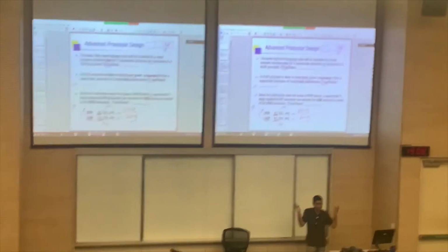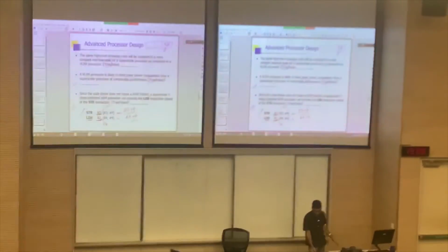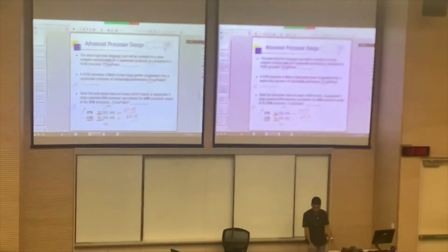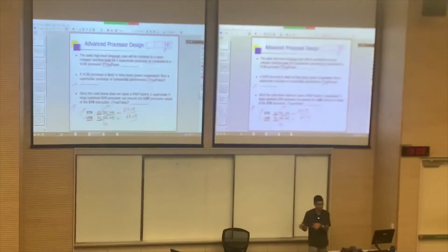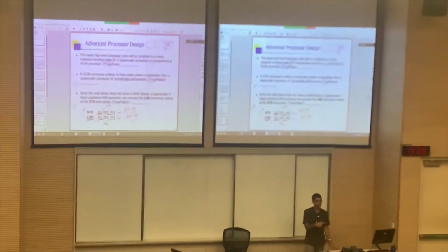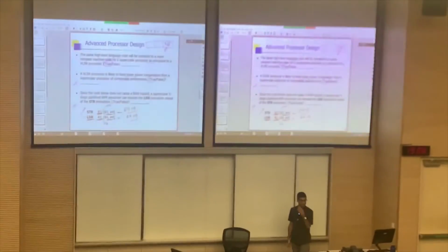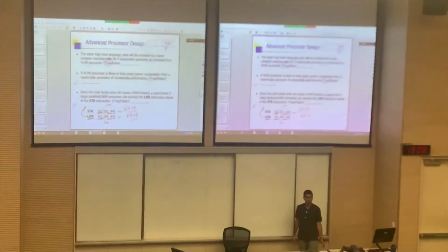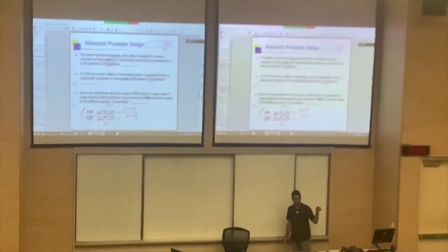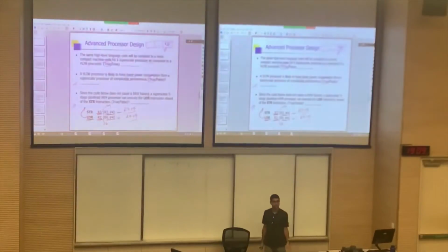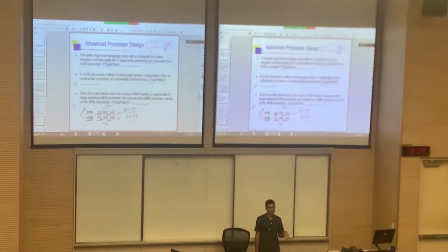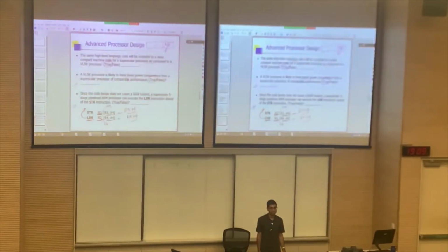And if there is a true dependency of any sort, you cannot push the dependent instruction ahead of the source instruction. This is the one which supplies the operand, and this is the one which takes that operand, right? If they are the same, then you cannot really push LDR ahead of STR. So if you do push LDR ahead of STR, you have to do it based on the assumption that they don't refer to the same location.